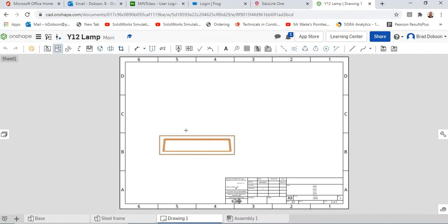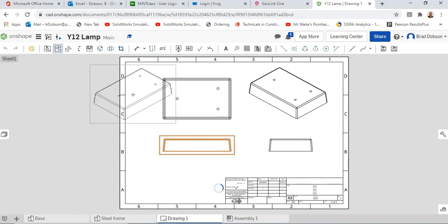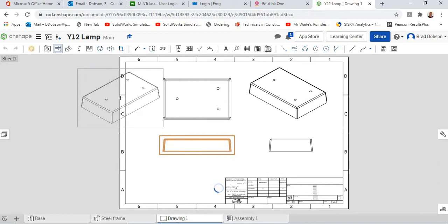Again, you'll see up the top here that the projected views has now been selected. So if I just move above, it'll automatically start producing the top view. Again, once I've done that, come back down, select, so click the left mouse button, it will then produce my side view for me. So again, really quick. Again, go back, click on it, go diagonally up, you'll see it can produce an isometric as well. It can actually produce isometrics any way you want, to be honest. It can do a bottom view, a different angle, all that. All these can be moved around, all that type of thing.